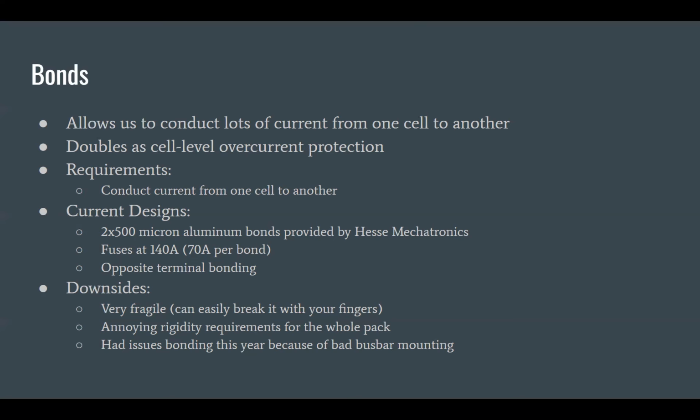The big thing the rules also very clearly highlight is that they want it to be as close as possible to the source of the power. If I were to be stupid and put a piece of metal in here and short all the batteries together on this connector, they want the fuse located as close as possible to the source of the power, the battery cell. So what they prefer is that we either directly connect the fuse to the cell or connect the fuse right there at the immediate first conductor connected to the cell.